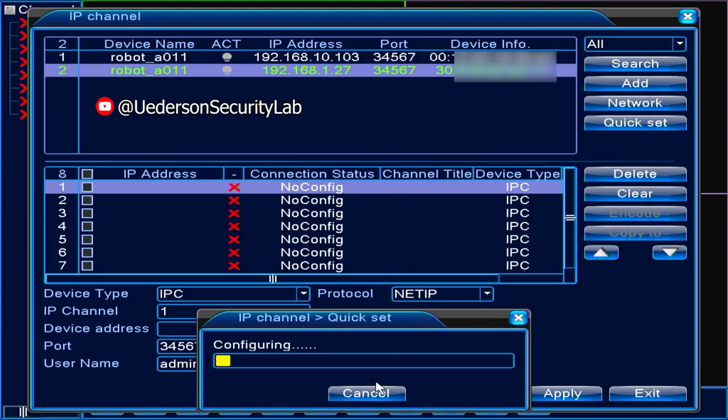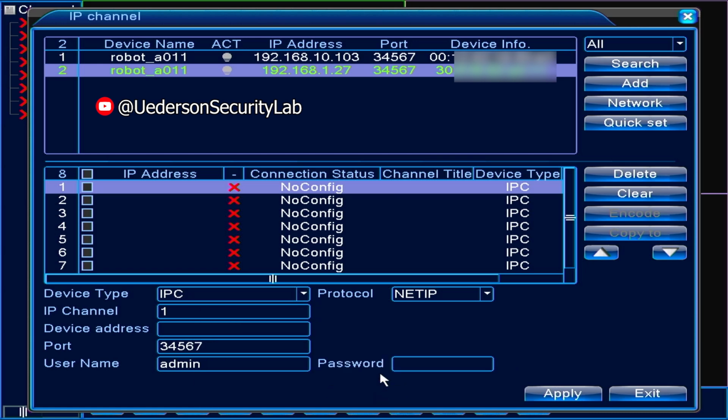As soon as this screen opens, your device automatically scans the network and lists any available cameras at the top. In these columns, you can see the device name, the IP address, the access port, and the MAC address. Right nearby, you can define your search protocol.